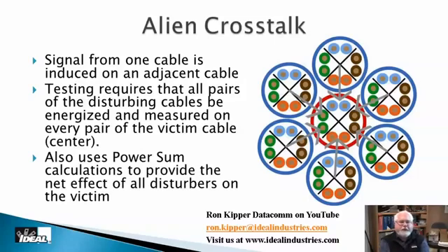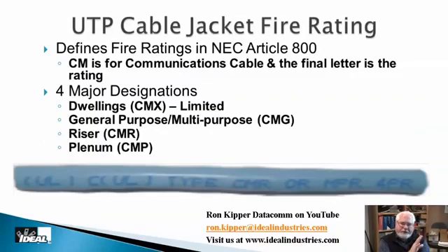There you go. Now, a very important parameter that you should know about any type of cable you buy and install in buildings is what is the UL or flame rating of this particular cable, and what's it rated for as far as the NEC, the National Electric Code, is concerned. And when you look at the National Electric Code, it basically has 4 designations here on cabling.